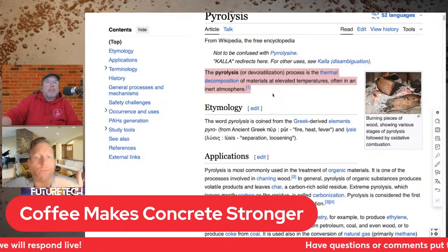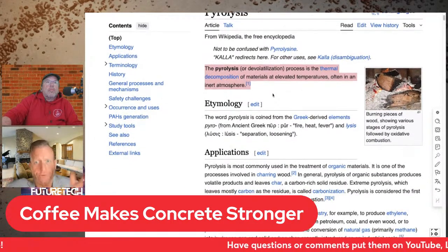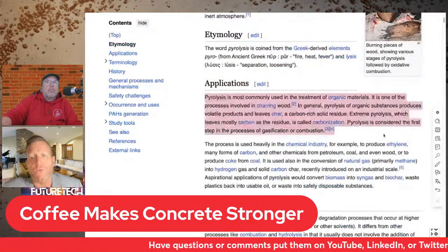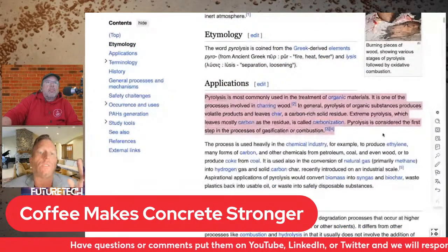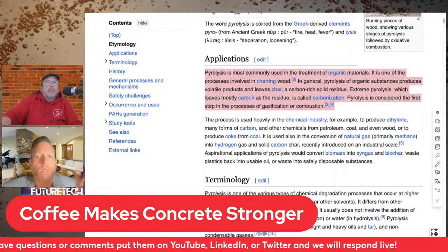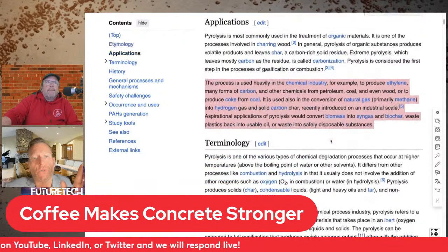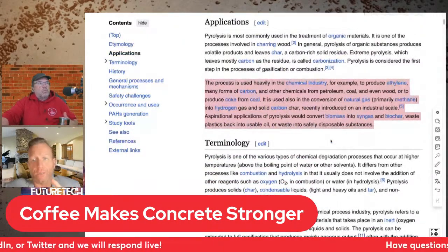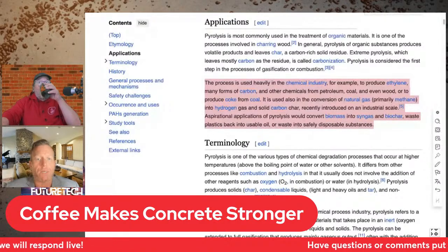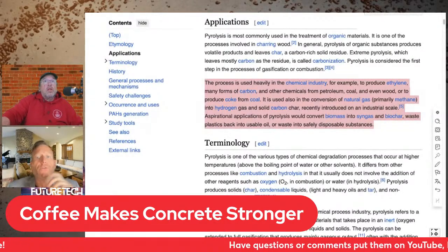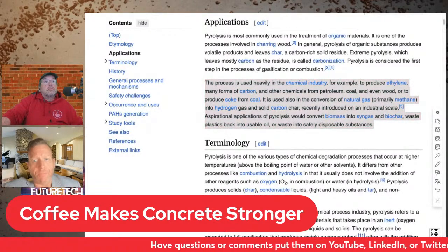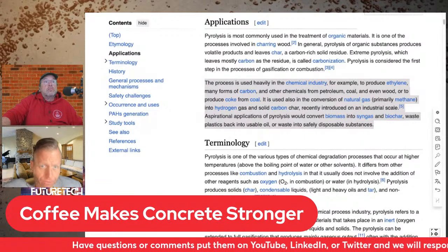At temperatures around 350 degrees Celsius, the organic compounds break down into biochar and pyrolysis oils and gases. If they were to use higher temperatures above 500 degrees Celsius, it would reduce the yield and weaken the bonding potential. So there's going to be optimizations needed to maximize both the quantity and quality of the biochar produced.